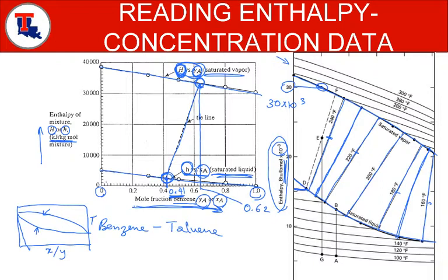You remember on here what you did was you located a temperature. I'm sorry, let me change the color. You located a temperature here on this axis, and then you drew a line. Your tie lines were very, very flat. In this case, remember the intersection points, this was X, this was the Y, corresponding in equilibrium. Here, the tie lines are not flat. They have a curve. That's the difference. So these two are in equilibrium.